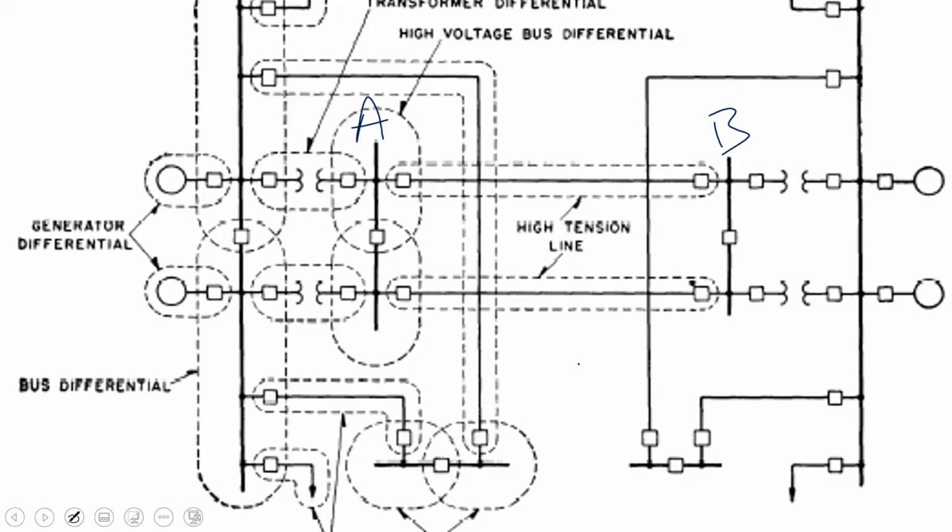Well, the breakers operate. First of all, the breakers in our home, the fault current passes through those breakers, or should I say the decision-making mechanism, the fault current passes through them, yes? In the power system, the decision-making mechanism does not carry the fault current. What it carries is a replica of the fault current. So the fault current passes through the lines, it passes through the CTs. Then the CTs take that information and send it to the relay.